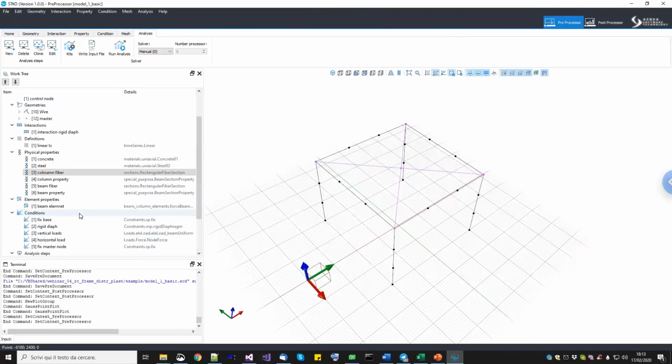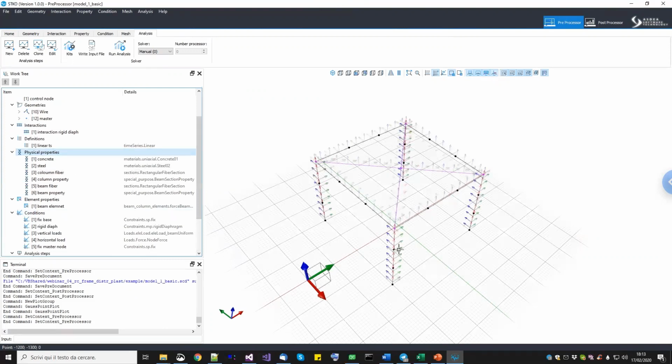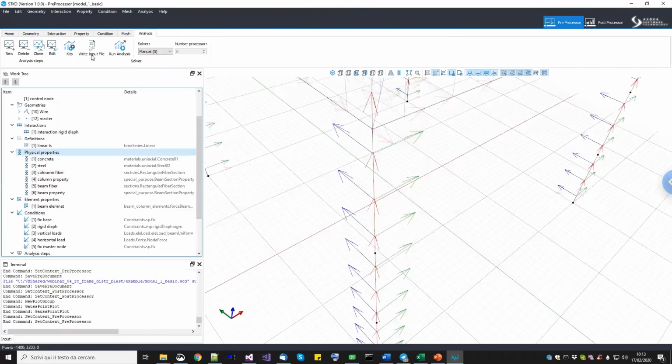So how do we include it? So the first thing is to define two uniaxial material models for the shear. Now we're going to add two different material models for shear in Y and X direction. Now remember that Y is the strong direction in the beam here.